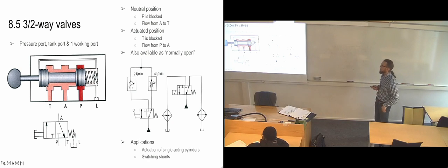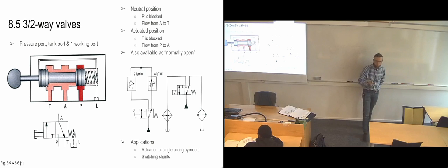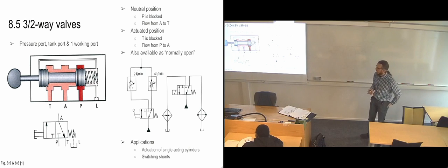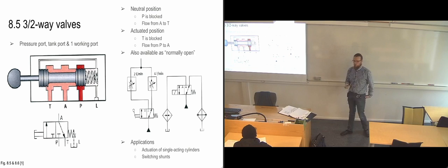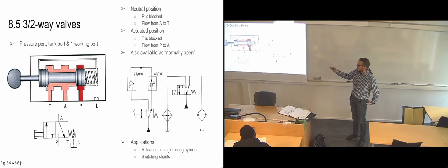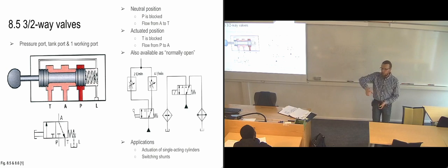So if you need to very quickly change the flow rate, it wouldn't be these are throttle valves, so they limit the flow rate to a certain volume. So this one is set to 2 liters per minute, and this one is set to 4 liters per minute. And what happens is that you could have just one of these, and then you would go in and you would manually adjust it from 2 liters to 4 liters.